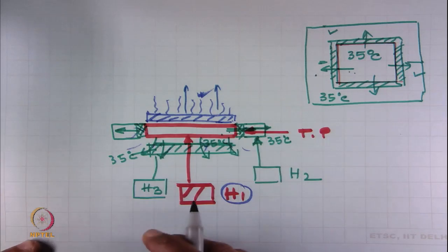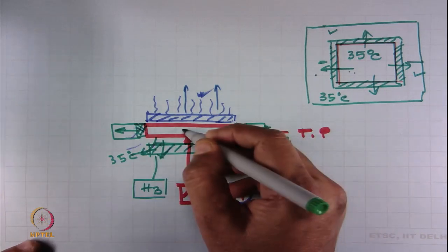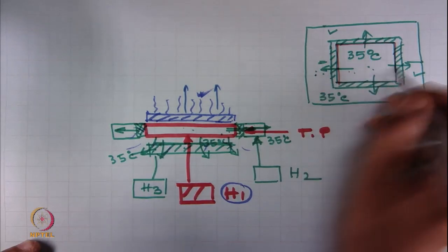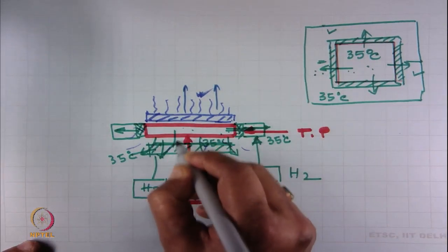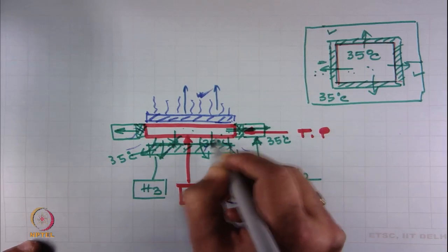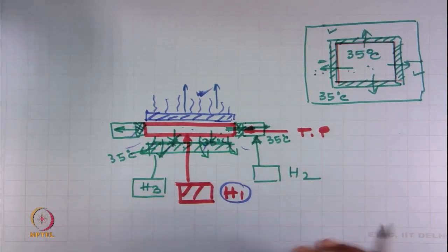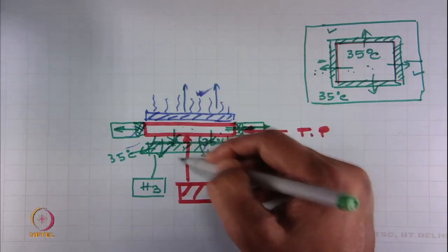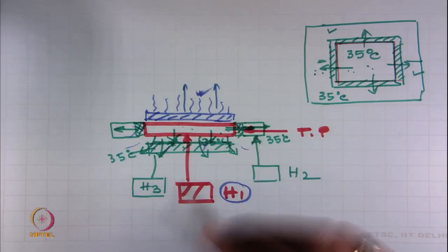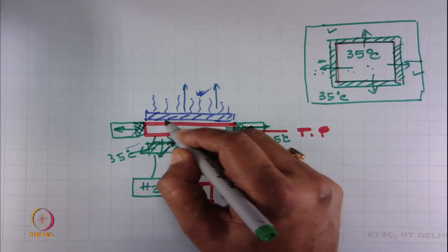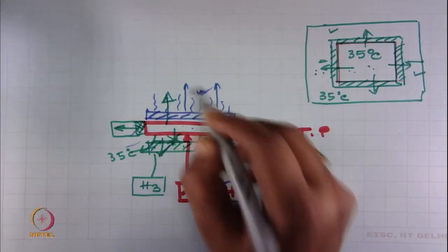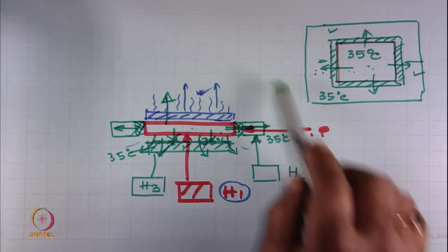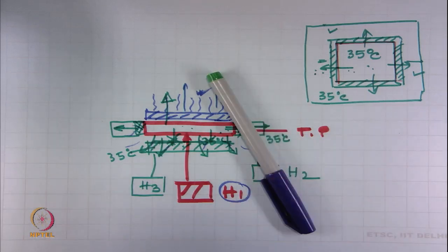That means, if we have no temperature gradient, heat will not flow in the bottom direction also. So, we have blocked heat flow sideway as well as bottom way, only one direction the heat can flow, that is the top direction, and in the top direction we have placed the fabric on the test plate,